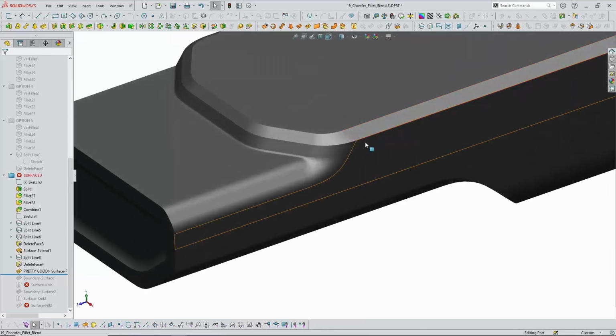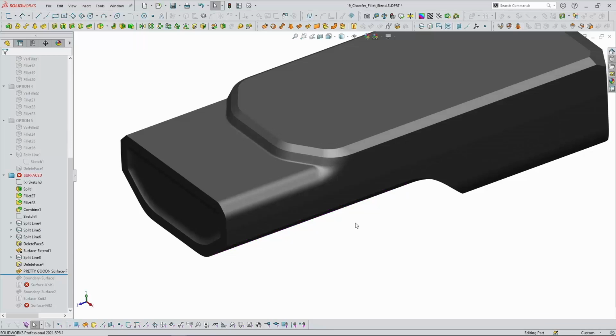This is looking pretty good, and ultimately this I think was the level of solution that we went to for prototyping. We weren't molding these parts yet, they were being CNC machined for some field trials, and I know that they were going to get hand sanded and painted, so this level of fidelity was fine for a textured part. I wasn't tooling the solution yet. If I had gone to tooling, I probably would have gone back and resculpted this area.